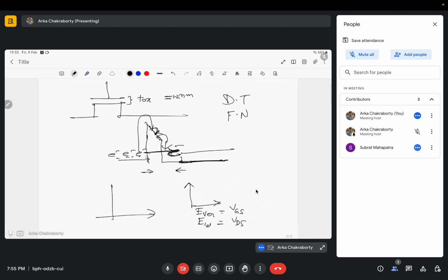Now what happens when we say initial, let me take an arbitrary shape. This is not the actual shape, I don't remember the actual slope. Say this was my initial condition for, say, 65 nanometer technology. Now I have shrunk to 5 nanometer technology. When I have shrunk it, I want my subthreshold slope to improve. It is improving, but if I only scale the lateral direction, the control of the vertical direction increases, and instead of reducing, it might increase. It might show something like this.